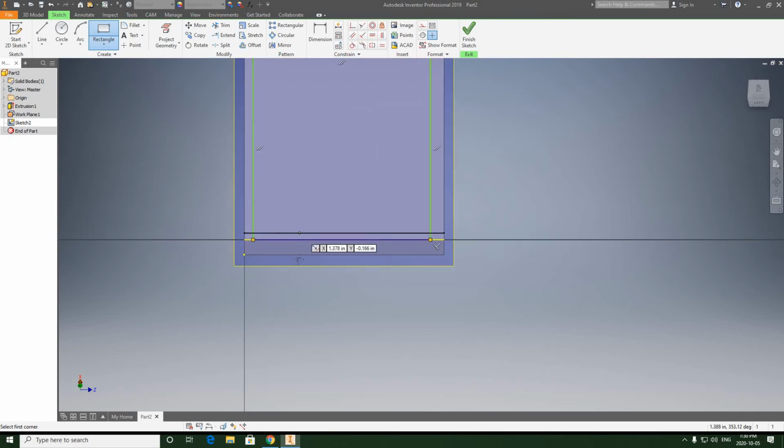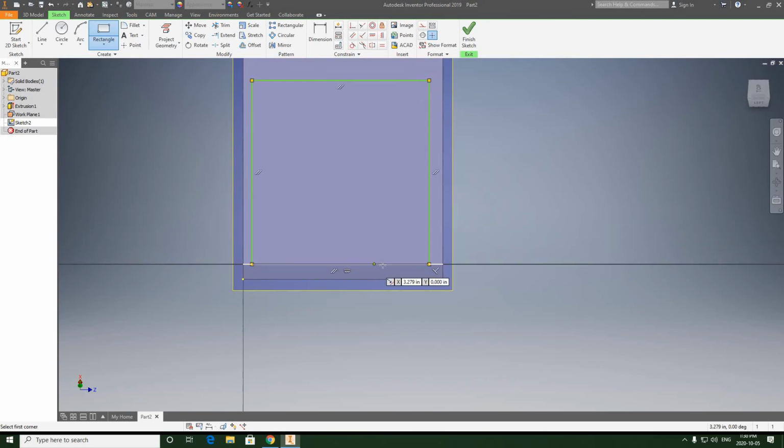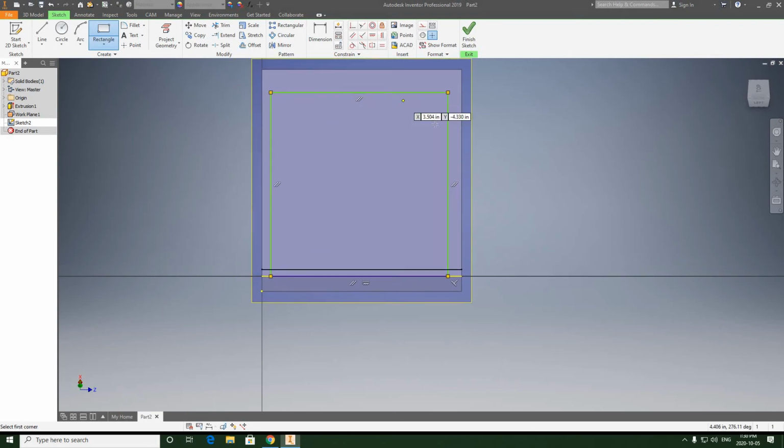So that means this isn't going to move from that edge, but I have the rest of the geometry green, which now I can constrain. So again, and I'm following along on the sheet, I'm going to run a general dimension from here to the edge of the base, and I'm going to update this to be 0.5. I'm also going to do the same thing on the other side.